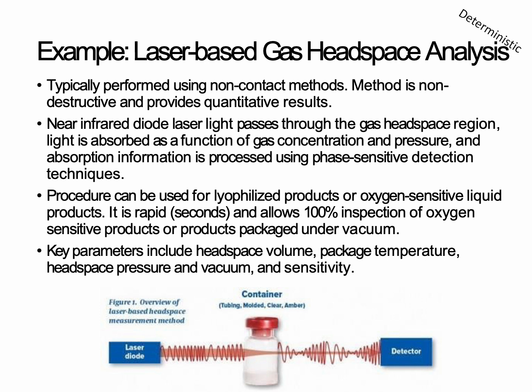Now, the procedure can be used for lyophilized products or oxygen-sensitive liquid products. It's rapid and allows 100% inspection of oxygen-sensitive products or products packaged under vacuum. Now, the key parameters include headspace volume, package temperature, headspace pressure, and vacuum and sensitivity.